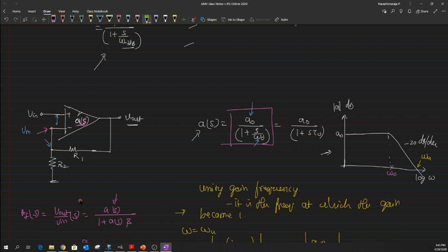In this case I have a small signal, I have this DC gain of a closed loop system, and depending on the factor of beta, I assume that beta is not equal to 1, and due to which I am just trying to draw a line assuming that this is my gain, and this gain will be almost constant till I reach the bandwidth of my closed loop system, and this bandwidth would be mentioned somewhere here as omega c, which is quite higher than the previous value of omega naught, and this is because we are using a logarithmic scale.